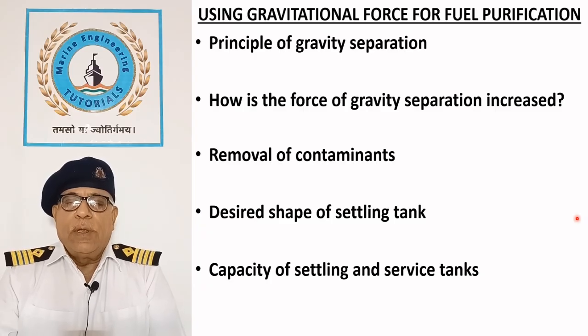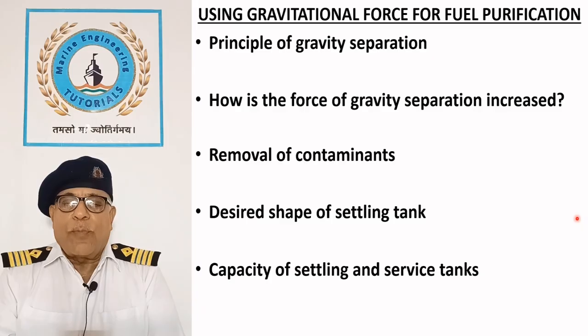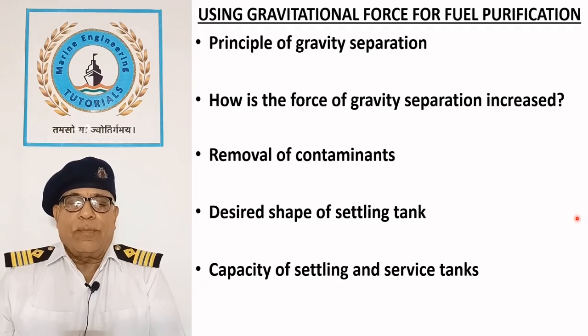Modern ships for unmanned engine room operations are equipped with one each settling and service tank of capacity about 50% in excess of the daily fuel oil consumption.